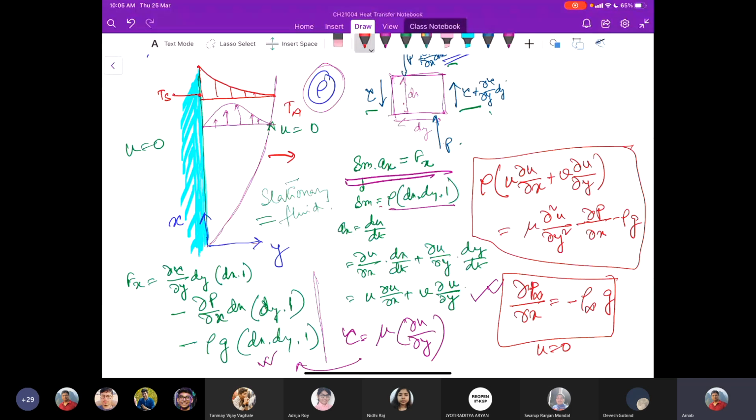So similar to forced convection in other cases, I will show you a couple of empirical relations that best describe certain scenarios. And we have to find out the best scenario for your problem to find out the Nusselt number and subsequently the heat transfer coefficient and so the heat transfer rate that we follow.